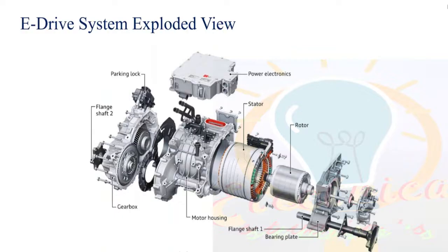If there is a misalignment, what will happen? It will damage the whole system inside. So the shaft should be completely balanced and aligned properly. And more than all these things, the rotor is a very heavy component. When it is rotating, it will develop a huge amount of forces. The forces acting as a load should be withstood by the bearings also. So the bearings also withstand the load created by the shaft when it is rotating.